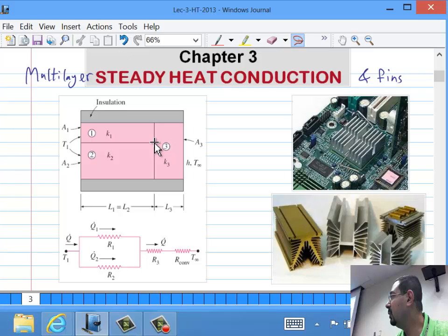Those fins are all those very long surfaces that you see on electronics and motorbikes. Anytime you'd like to cool and the cooling is not efficient enough, you add those fins. And do you know why that would help? Because of the area. Eventually, the last Q is by convection. It's the air around your motorbike when you are driving on the highway, or the air that the fan is hopefully blowing across that surface. Eventually it's by convection, and that convection is hA delta T.